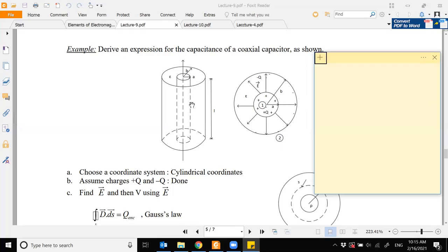This is determined by the specifications of the coaxial cable, because of this capacitance which we are finding, that is the capacitance created between these two conductors, and the resistance, it forms a sort of filter.